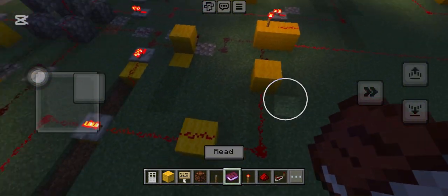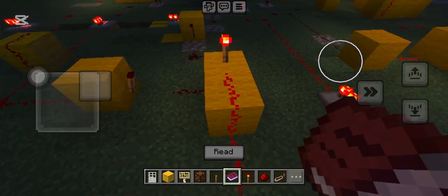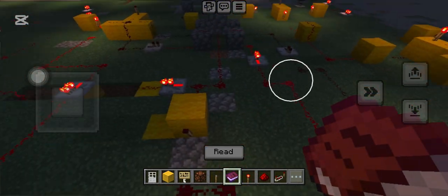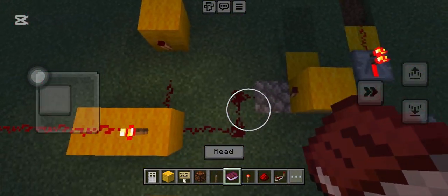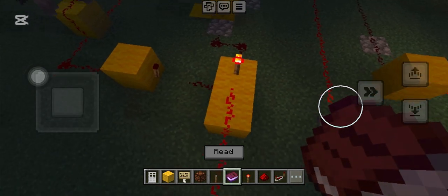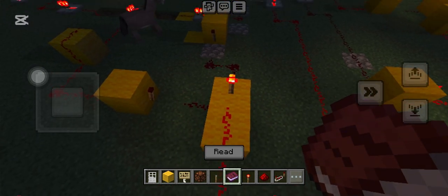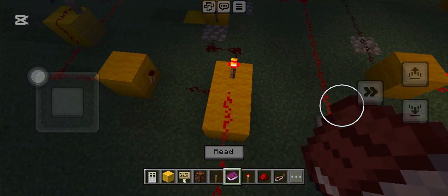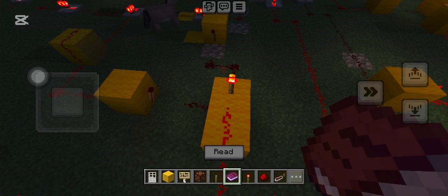Now let's go to our XOR gate. The XOR gate is a real sum calculator. It combines the OR gate with the NOT AND gate, or what we call an inverter. The XOR gate lights up only when the two inputs are different, which means one is on and one is off. For example, if A1 and B1 are different, the answer is 1, but if they're the same, the answer is 0. And this is our bit 1 sum.